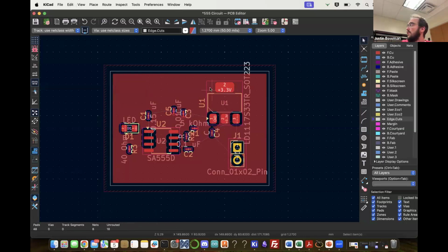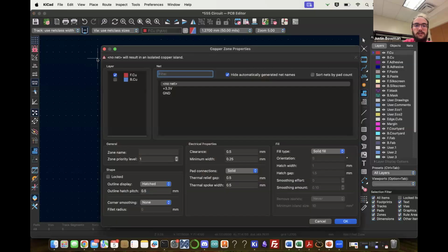You have your edge cuts. And now you want to get a fill zone. So if you click your top layer, FCU, and then go to fill zone, which is under the orange circle, add fill zone, and then inside that small box again, outside of the box, you're going to click, and a window will pop up.